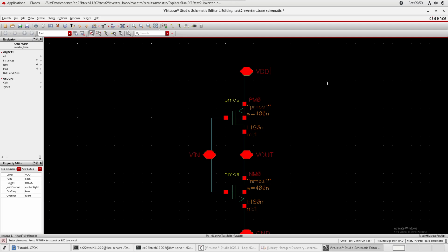It doesn't say the VDD is 1.8 volts or 5 volts or what. So better to keep something like this. And if you put dot or something in your net name, that may also cause issues. Hence, try to use like underscore or something. Sorry, try to use like p or something instead of a dot, a point.